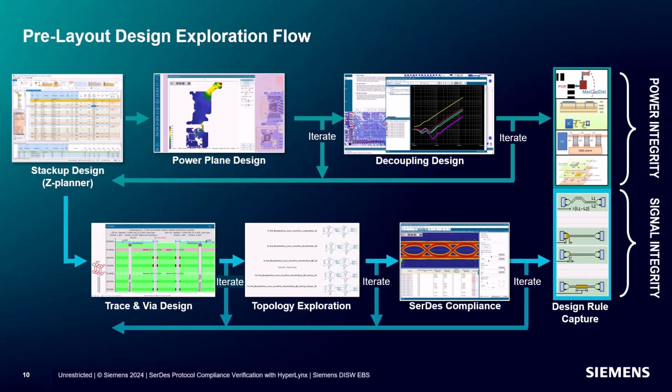We'll explore two types of pre-layout flows: a power integrity flow, which starts with stackup design and then includes DC and AC power integrity. In some cases, DC and AC power integrity are additive. The power degradation at the IC is the sum of the two, so we need to adopt a budgeting strategy for how much voltage we can afford to lose for each impairment. In other cases, they're relatively independent, so our budgets can be more relaxed.